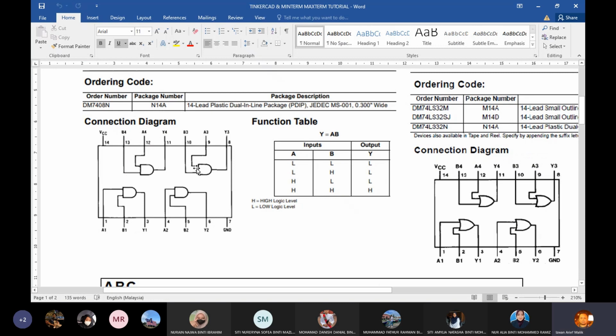So this is what is available in the 7408, the long black one. Inside it there are 2 input AND gates. Okay, AND gate, AND gate, AND gate, AND gate. Each of them has 2 inputs, see? 1 2, 1 2, 1 2, 1 2 and output 1, right? So these pins represent where the inputs and outputs of these AND gates are.